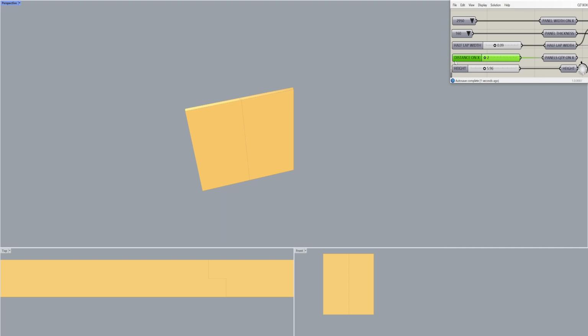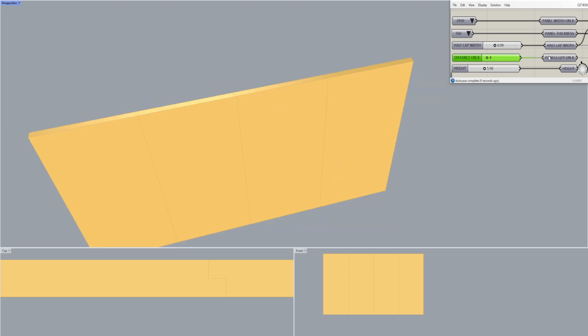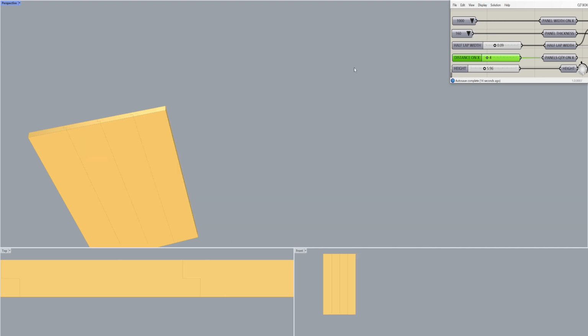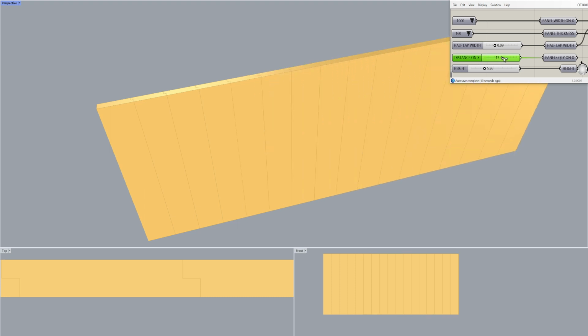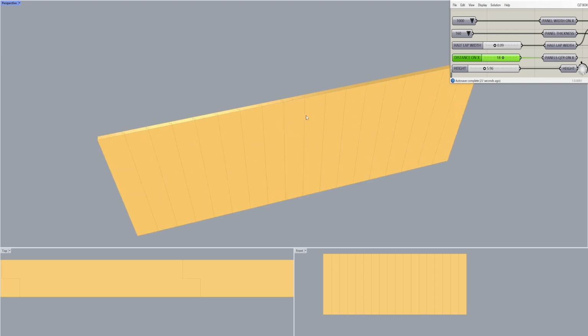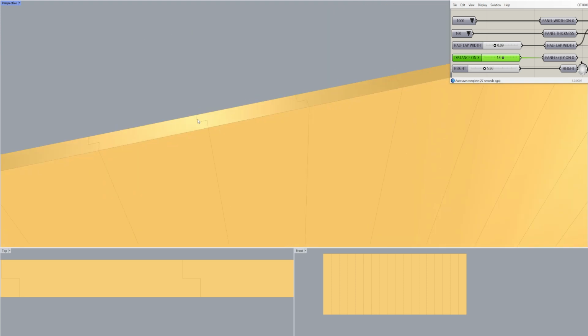So for example, here we've got two components, and if I start to increase this, you see it starts to automatically add a new panel of that width. So if I change that back to 2.5, you see it goes smaller. Back to 1000, gets smaller again. So this is just adding new panels along a length. And that's thinking about the component sizes here. So that line from there to there is, in this case, the way I have set it up, always going to be 1000. And that's the optimized size that would get cut out of a nested mother panel.